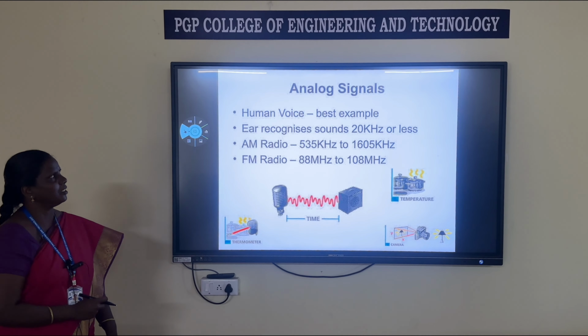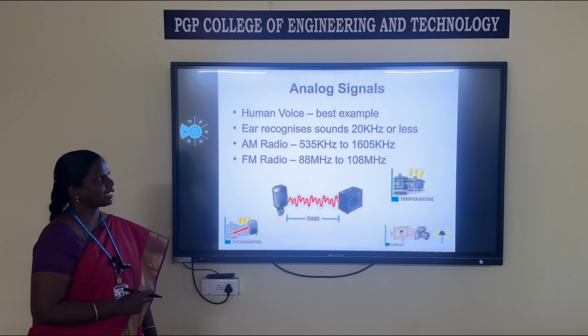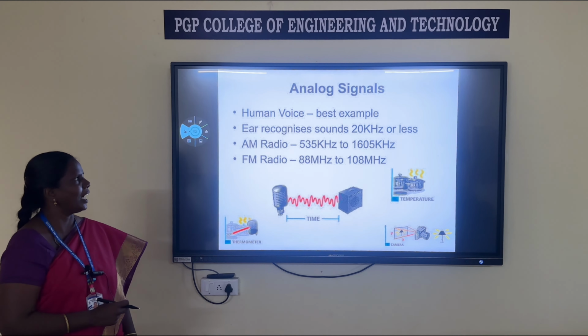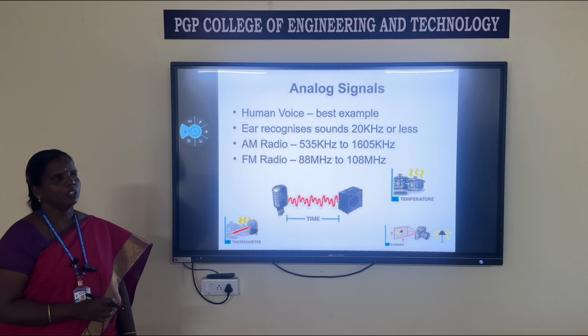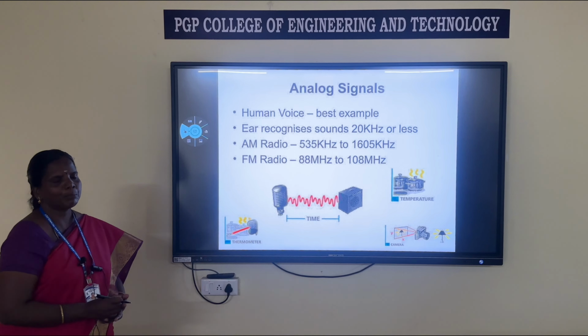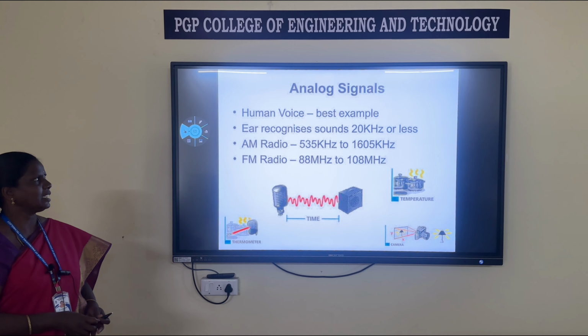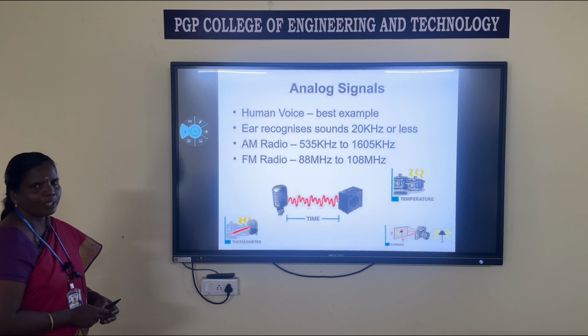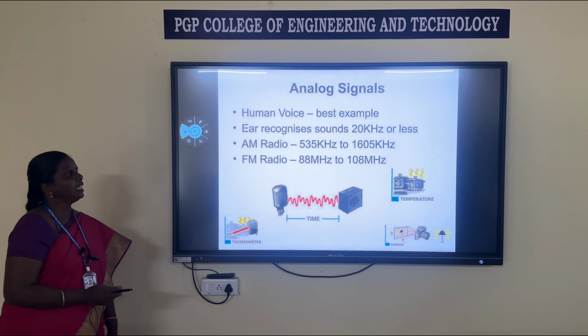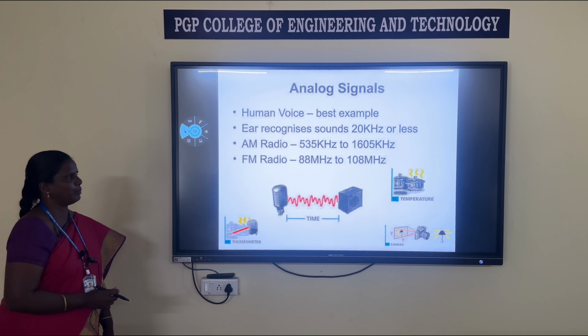Analog signal. One of the best examples of an analog signal is the human voice. Our human ear recognizes sound up to 20 kHz. In AM radio we use 535 kHz to 1605 kHz. FM radio works in the frequency range of 88 MHz to 108 MHz.